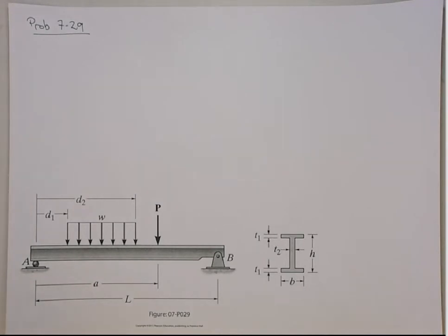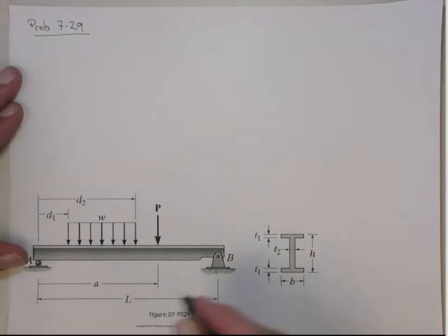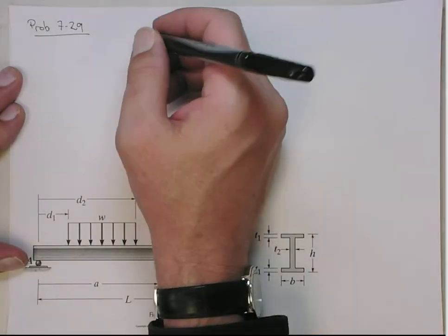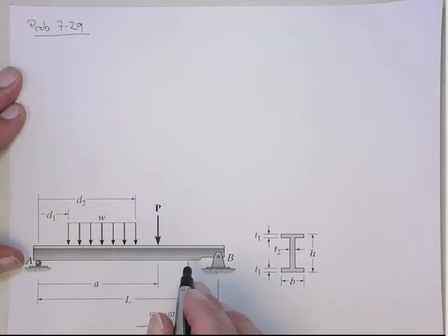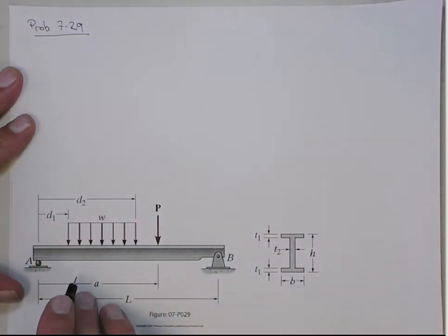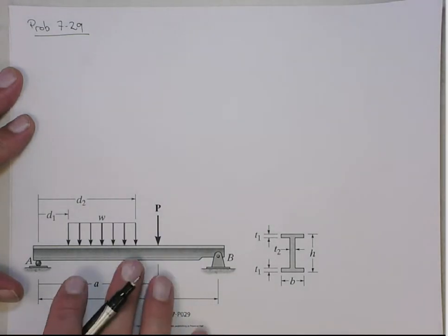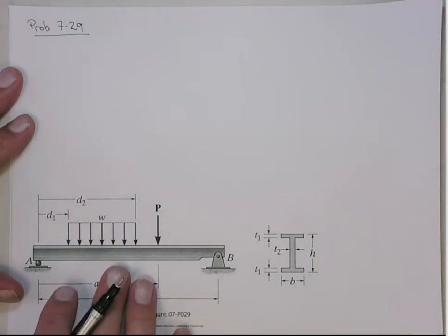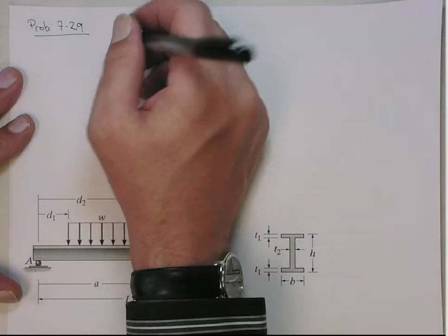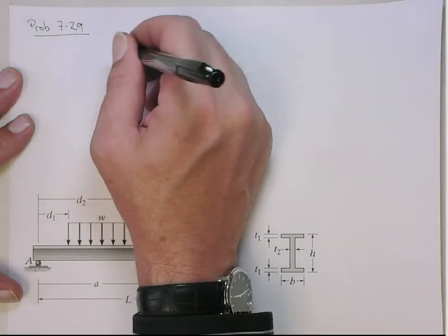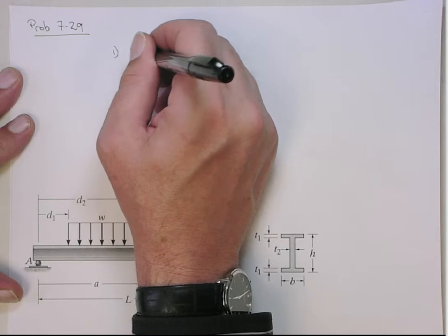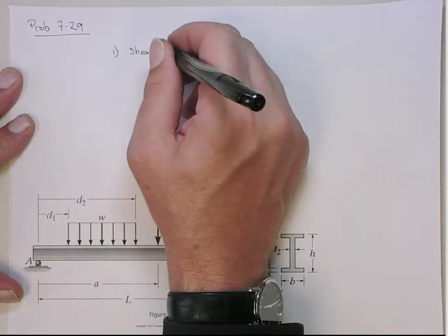So let's outline the steps we would do by hand and figure out how we would translate that into a program. The first thing we need to do is, we know to compute the transverse shear stress, we need to do VQ on IT. We need to get the V. So we need to be able to compute the shear diagram, or the shear forces.